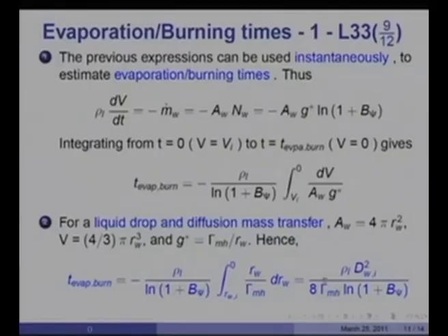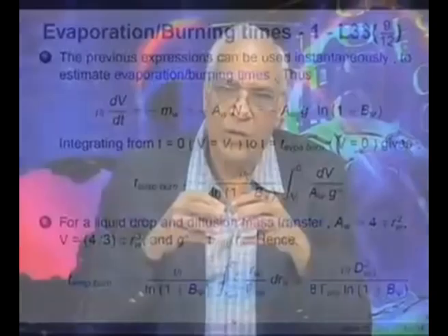In stagnant surroundings, this would be considered a guidance for atomization of fuels, atomization of, let us say, milk which is to be dried into a powder, or in a cooling tower where you send hot cooling water for cooling purposes. In a shower, you want to reduce the diameter as small as possible, so that you get very quick drying and a smaller dryer or cooling tower.